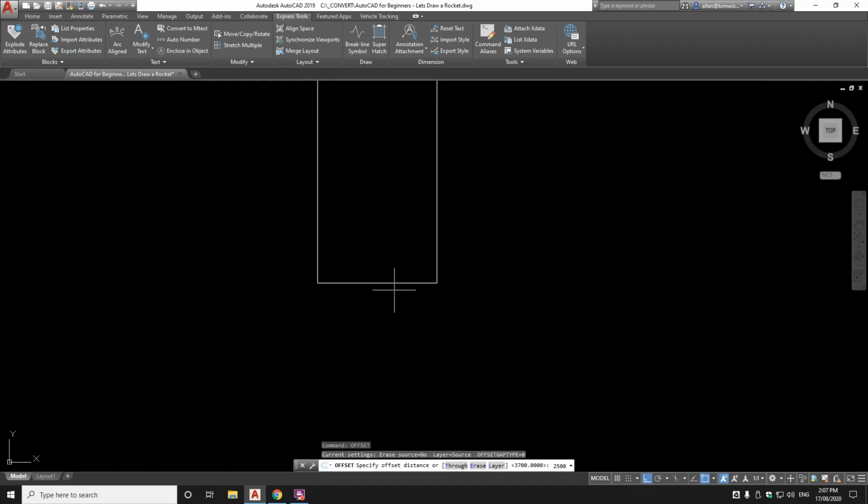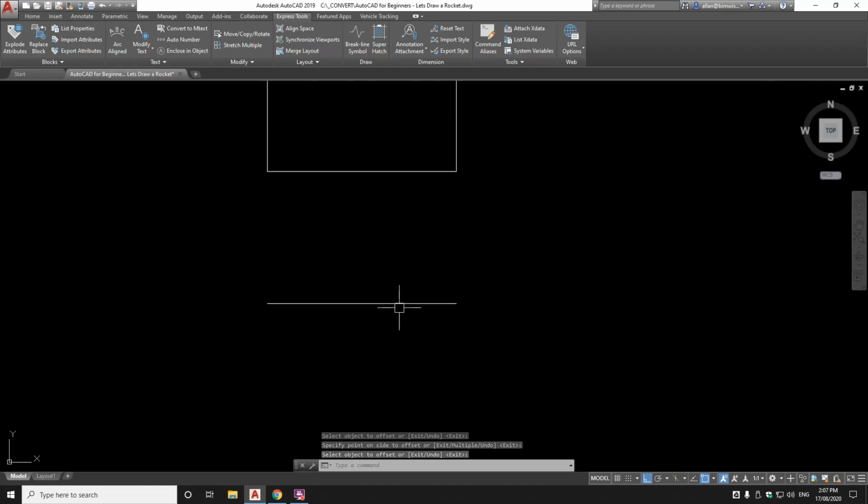2,500. Select my line, click down there. There's the start of my bell. I want it smaller than the top above. I'm going to use the scale command, S-C-A-L-E, scale.